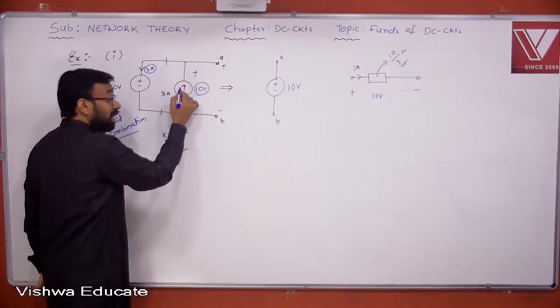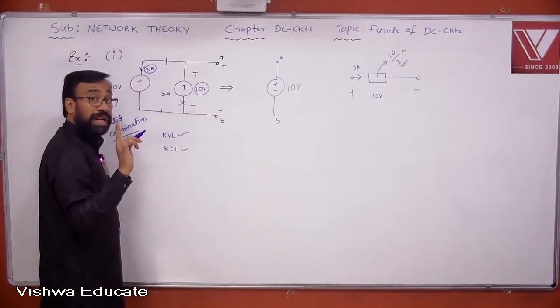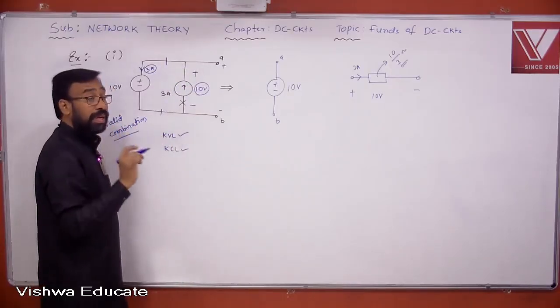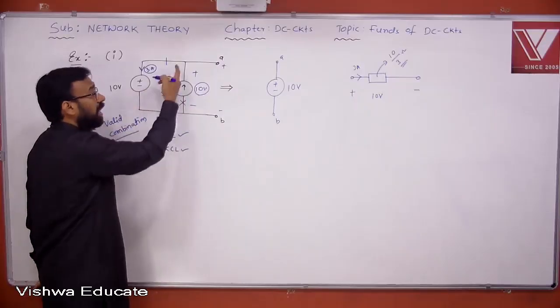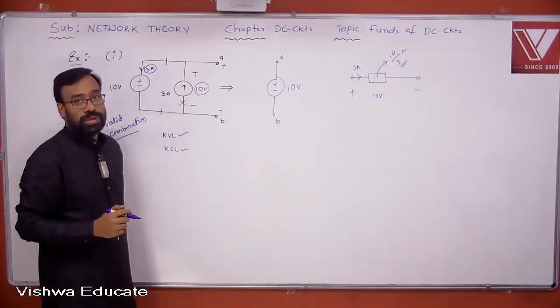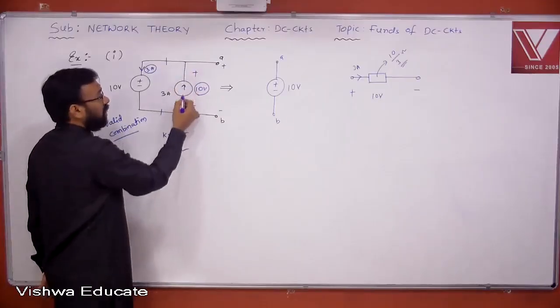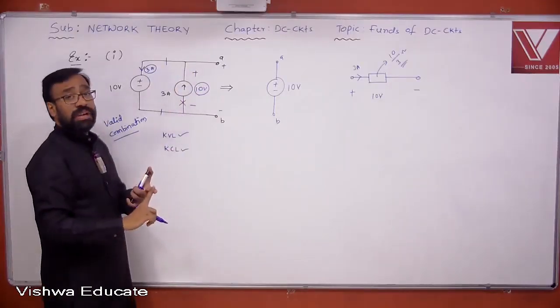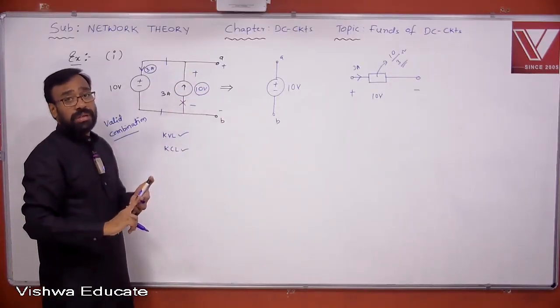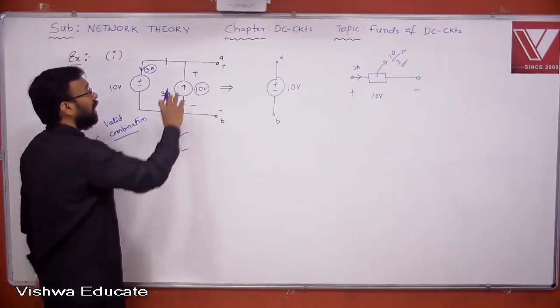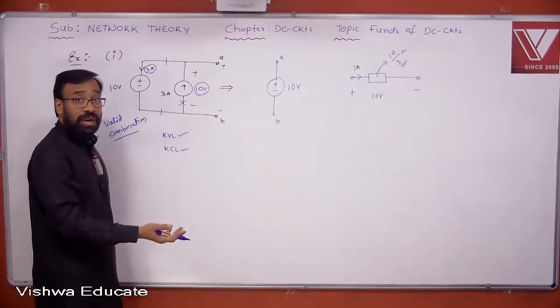If you have an inductor, no, an inductor cannot be taken. What will happen if an inductor is taken? If it is a DC source, it is acting like what? A short circuit. So that is not possible. So who has a possibility to sit here? A current source, resistor, capacitor. Any of these elements, even if you place them across this, can be neglected all the time.